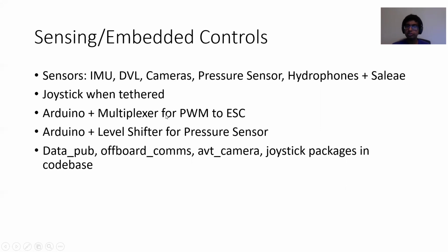We're able to control this multiplexer, which sends PWM signals, specifically how low or how high, to the ESCs. The ESCs are the things that control the thrusters. Using this, we can set the speeds of the thrusters. Namely, the PWM sets the speed. The ESC does the low-level work of converting the PWM signal into a 3-phase AC value, which is what the thruster uses in terms of power. I should also mention ESC stands for electronic speed controller.